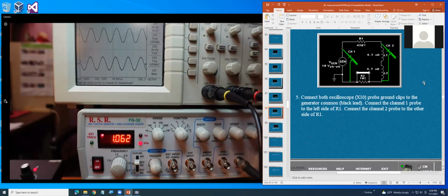But if you do auto measure, it messes up your thing, because one channel is 5 volts and the other one is 1 volt. Exactly. Right now you're using the manual, so absolutely never press auto set measure when you're doing math. When you press auto set measure, it erases everything.